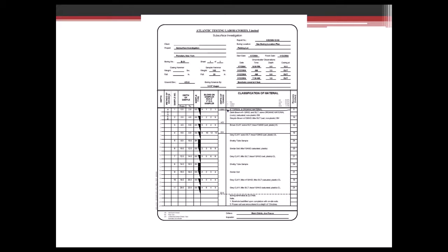Again, like I said, these 2 borings were in a parking lot area that was originally supposed to be in the building footprint. And what we did is we did the first boring first, that I showed, and then this one next. We were getting the split spoon and the Shelby tube samples so that we could do consolidation testing. And this is where the interaction between the geotechnical engineer and the structural engineer is very important.